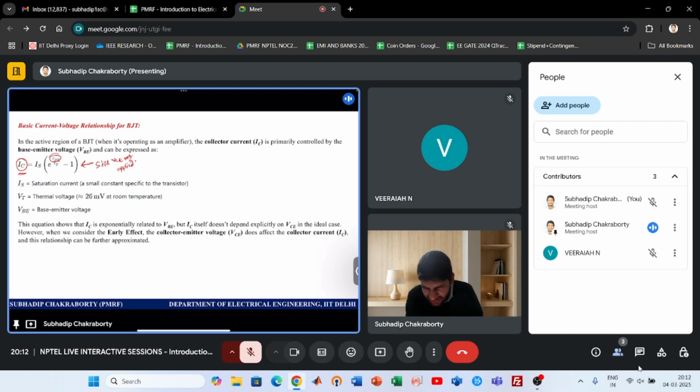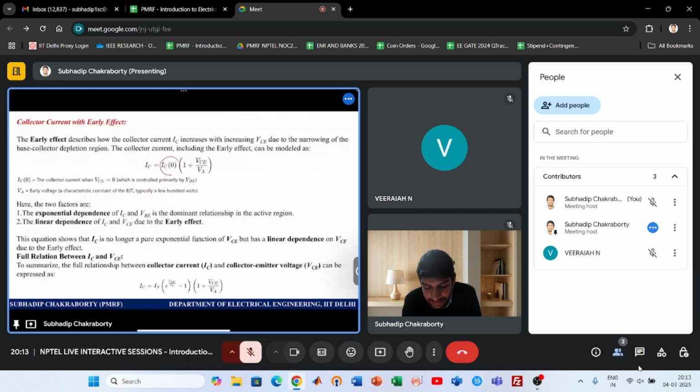How applying VBE works is basically the diode equations with some modifications, right? They're all already diode junctions, PN junctions, so we'll follow them. When VCE was 0, we know the formula, and the role of VCE on IC is still linear, because in the linear region you can see some increment, but very small.